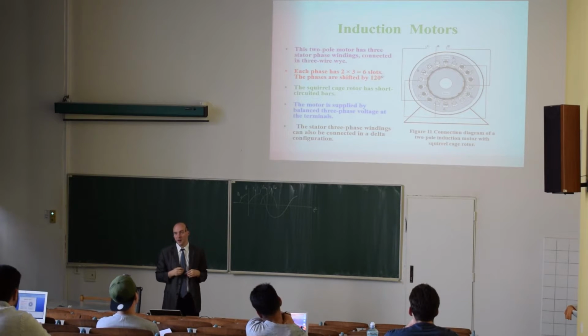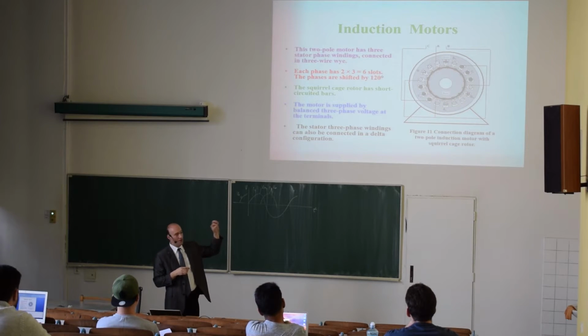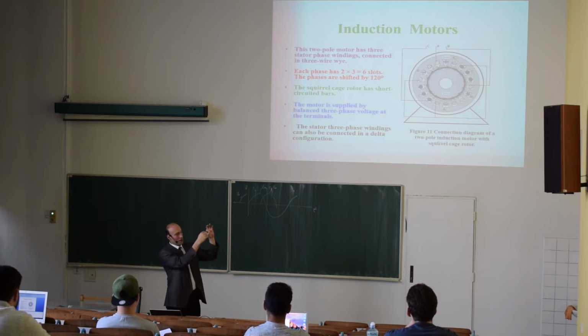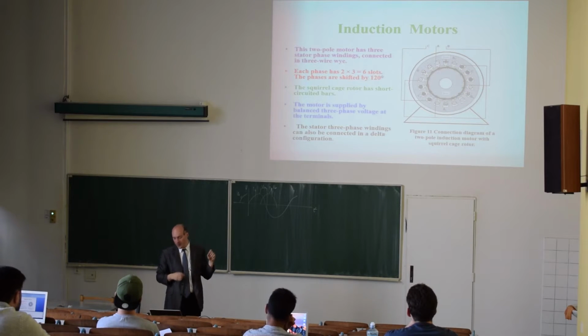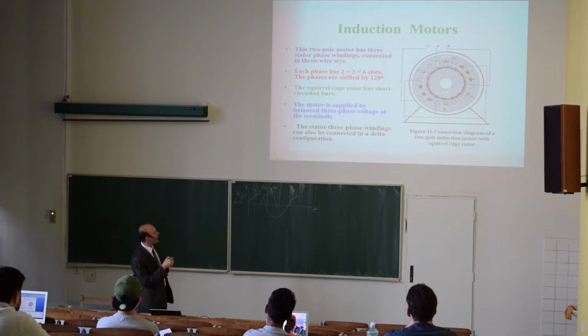But why will it spin? It will spin, but why? You have a fixed wire that's standing still, and you have a rotating magnetic field. So because of the change of magnetic flux, we will induce voltage in the rotor winding. So there will be an induced voltage that is being created in those slots in this winding.